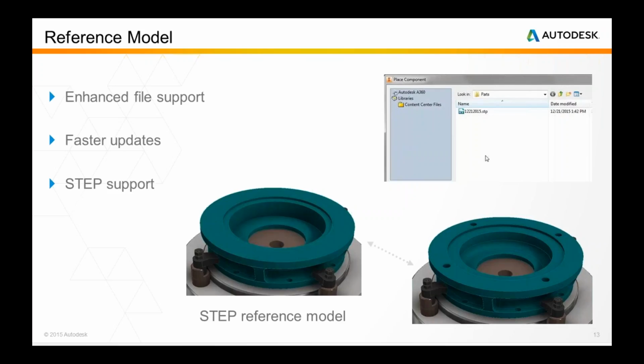So let's take a look at that one. And this is for two different types of files. First, the STEP file or STP file is a pretty common generic file that gets transferred around to a lot of different companies. You can usually export to an STP, and then it can be pulled into a lot of other CAD systems. It's very useful, like an IGES file.